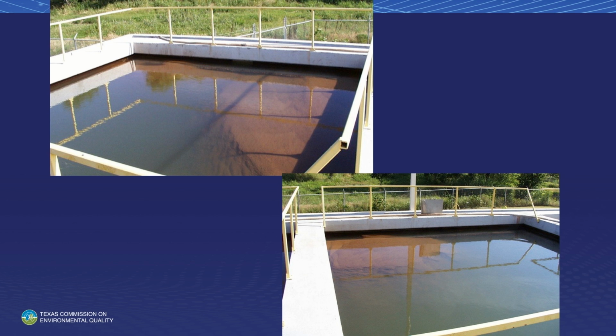And when you change velocity and you've changed the effective surface area of this sed basin, you change the settling characteristics. So the flock has to settle faster than the upflow in that sed basin. If it doesn't, the upflow in that sed basin will wash that flock particle out of your sed basin and right on top of your filters.